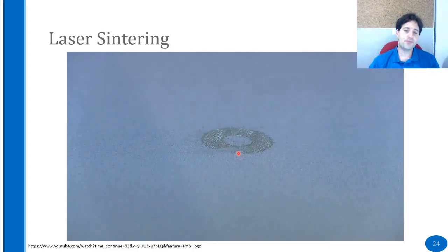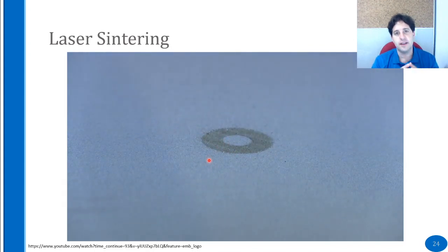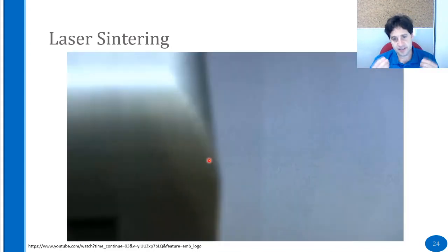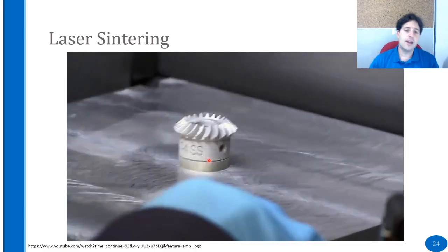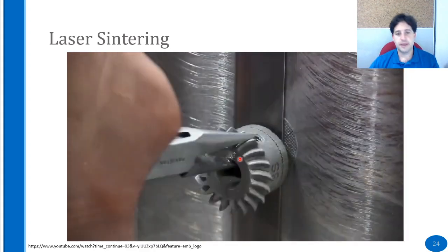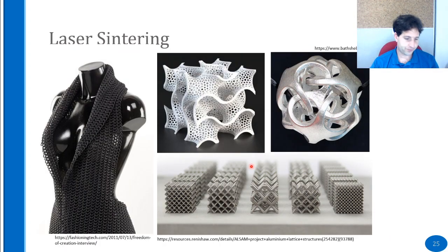And usually, the biggest advantage of this technology is that this bath of powder can be metal. There are a lot of metal SLS printers, and it can also be some plastic like nylon, but I think metal is the biggest advantage. It generates metal parts that are really strong, as strong as parts generated in another manufacturing process. Here again, you can achieve rather high detail level and resolution, and it's being used for art as well as for functionality that we'll see a few examples of later.